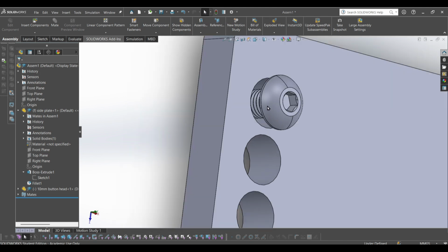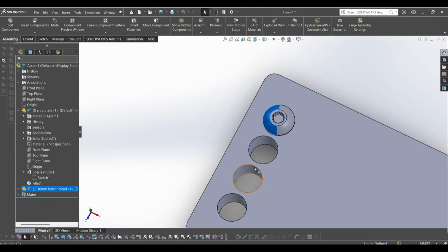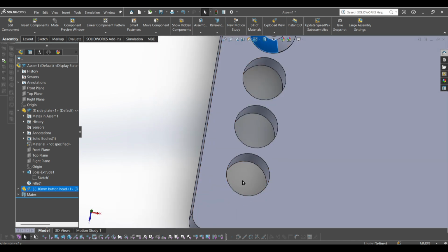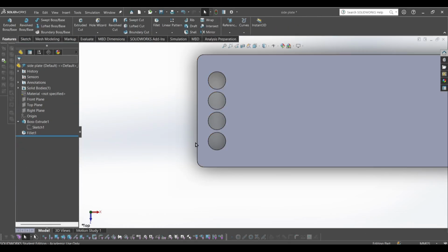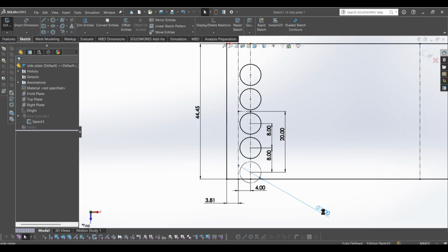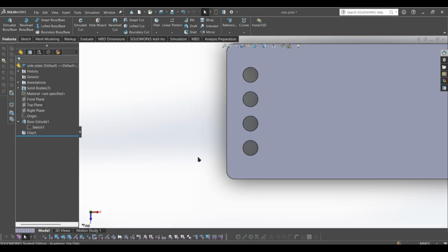One is because you have the head of the screw almost going through the hole, and 2, now these holes are super duper close to each other, and that increases the chances of the snapping and this just becoming one big hole instead of 2 separate holes. And you wouldn't be able to change that because you don't want to change the spacing, you just want to change the size of the hole and tolerance the hole. So usually the sweet spot is 0.5 to 1 millimeters, and you'll get used to doing that more as you make more parts and print them with the 3D printer.